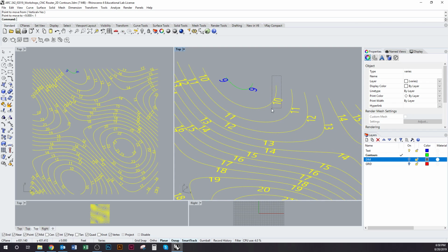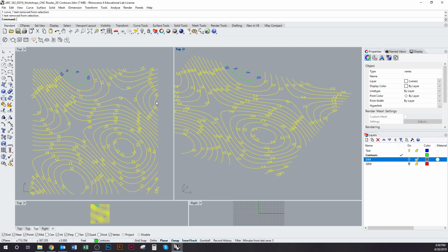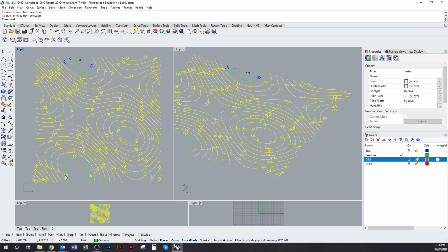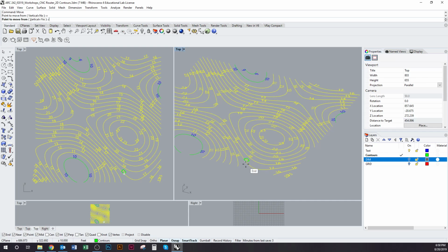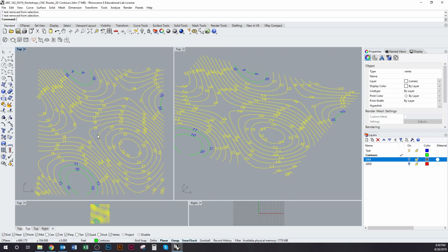And now I would go in and deselect all the contours that are marked as 10. And you can choose to move the labels as well if you want. That won't be too important once we've got everything in position. So it looks like there's no more 10, so I would move it again. Move, vertical, 1, enter. And I'm just going to do this for each set of contours.